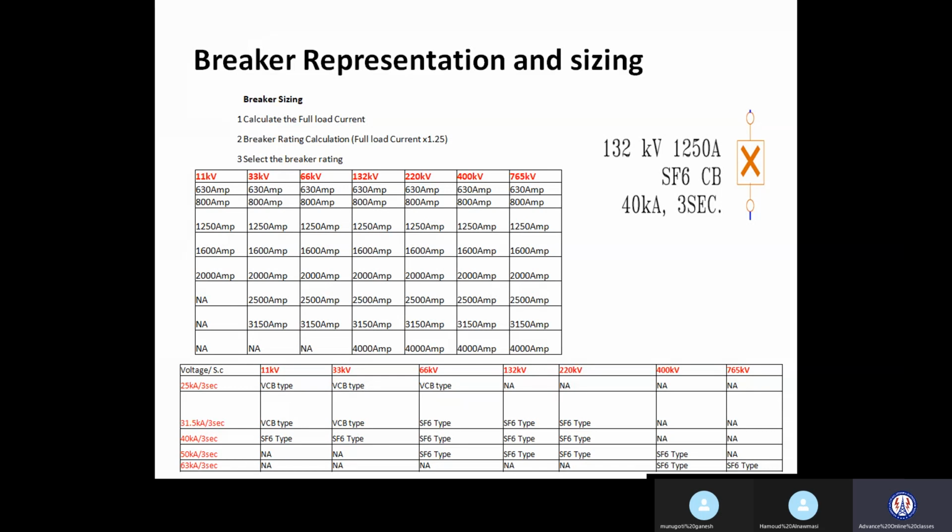But once you go to a medium voltage system, when the breaker opens and closes there is a huge arc because of the high voltage. So that arc you cannot quench with the help of an air system. You require vacuum or SF6. Understand why we are using an air circuit breaker in low voltage?